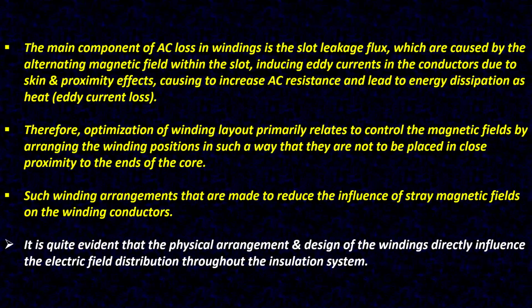The main component of AC loss in windings is the slot leakage flux, caused by the alternating magnetic field within the slot, inducing eddy currents in the conductors due to skin and proximity effects, increasing AC resistance and leading to energy dissipation as heat, that is eddy current loss.